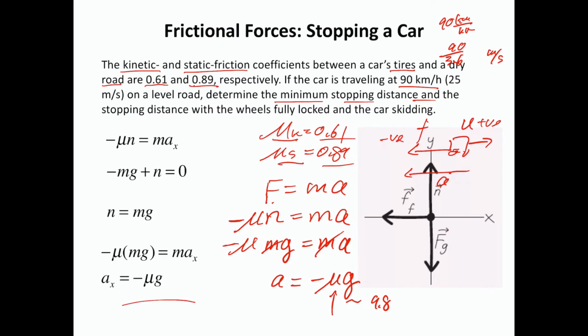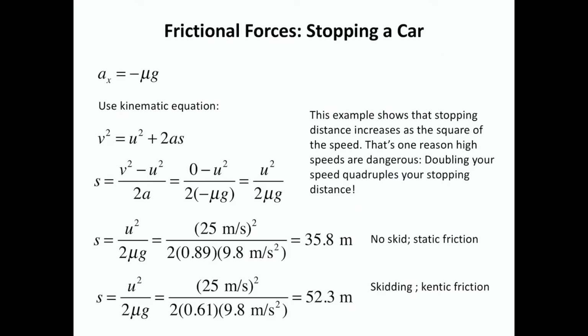Now, we start from here. Go back to some of our kinematics. So it's easy now. We can apply the same equation. We know now this is your force, this is your initial, this is your final equal to 0. Initial is where you cut the engine off. And I know now the a is negative mu g. Therefore, I use this one. You want to find the distance. We rearrange your equation. Can you see it? Plug in v equal to 0.